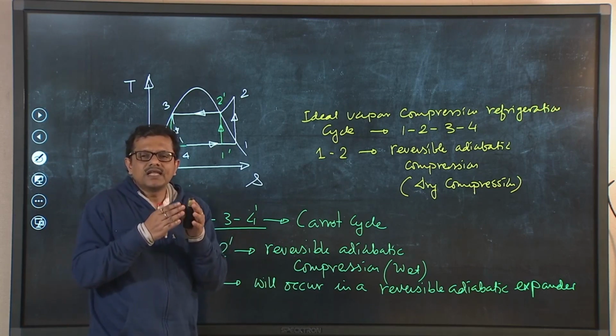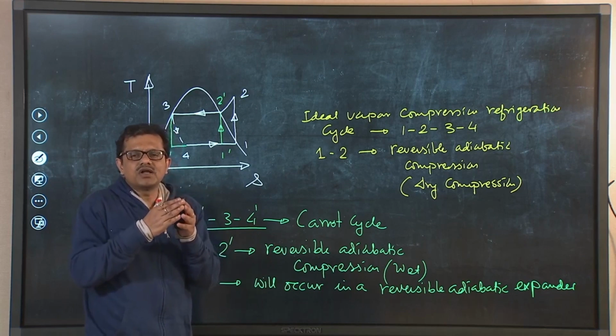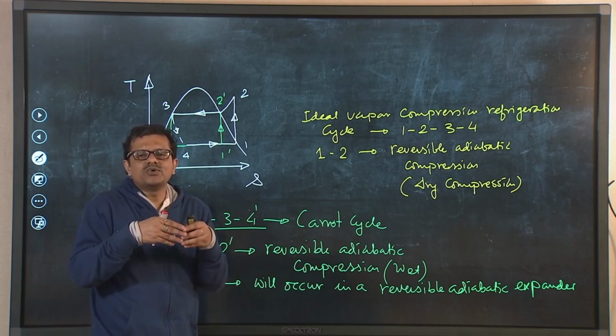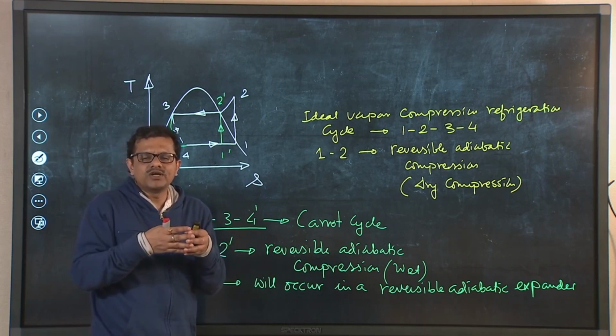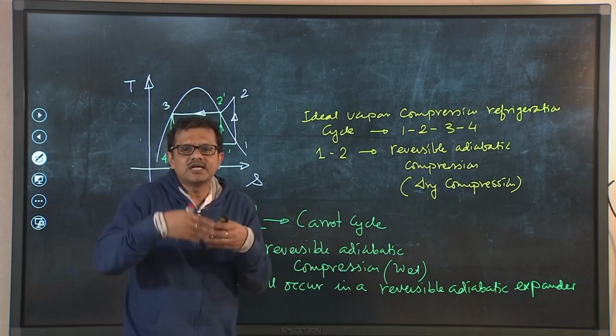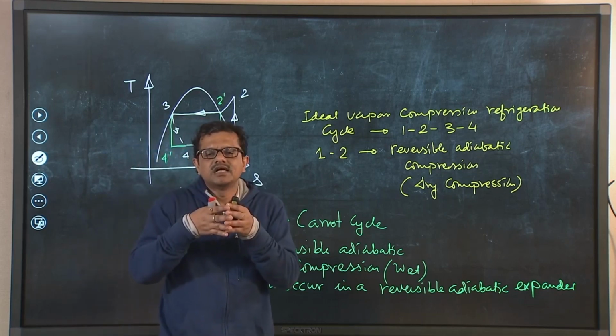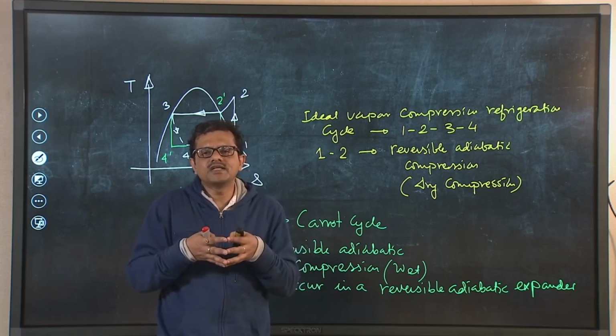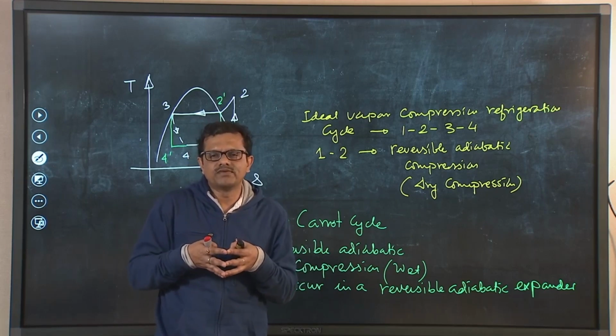Typically, the gap between the piston and cylinder wall is filled with a lubricant. Now, when liquid molecules penetrate into this passage, that will wash away the lubricant, and this phenomenon is known as the lubricant wash away phenomenon.